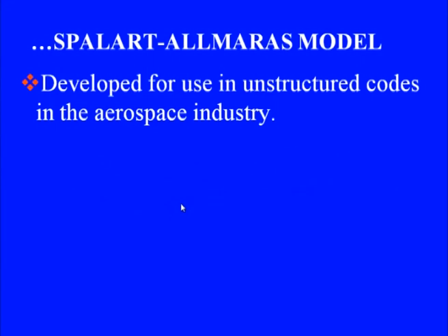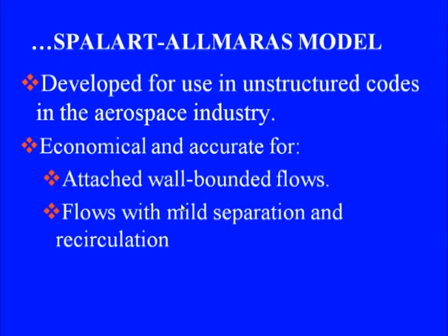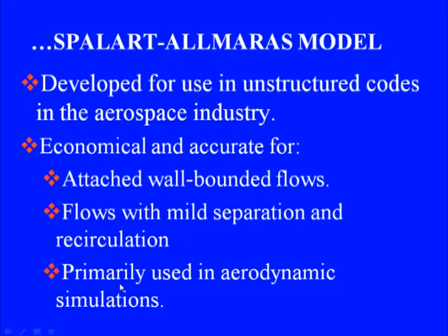Now this was developed primarily for use in unstructured codes in the aerospace industry, and it is economical and accurate for certain types of attached wall bounded flows and flows with mild separation and recirculation. Please remember, as we described earlier also, that it is primarily used in aerodynamic simulations. So we are not going to have any detailed look at the equations involved. If you are interested, you can pick up any book, like for instance Versteeg and Malalasekera's book, or any other CFD book, which can give you details of this model.